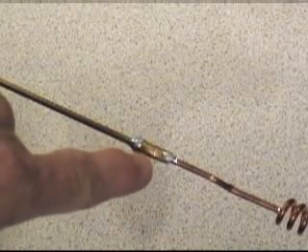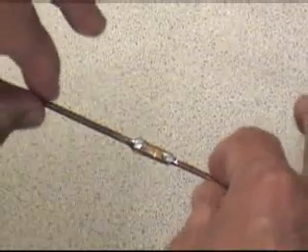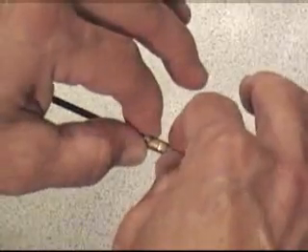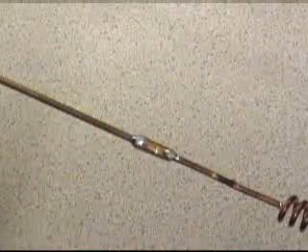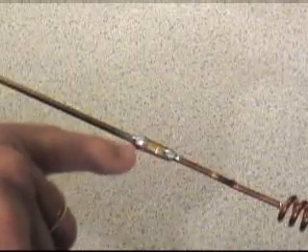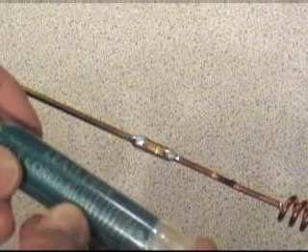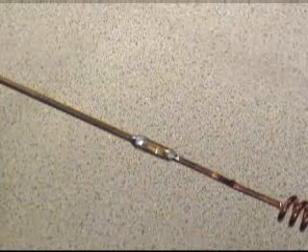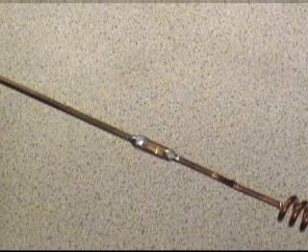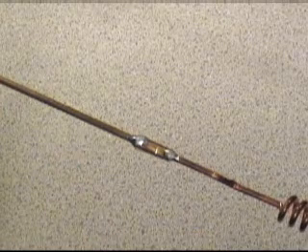On the standard model, there's a crimp connector. The radials slip into it and are crimped down. There's no solder. You add solder here, and this will make this antenna much stronger and also help reduce noise in it. Flux cord silver solder has a lower melting temperature, and it actually is a stronger bond.